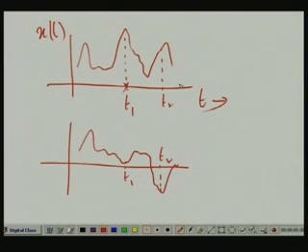This is possible. Now in the case of a stationary process, we assume something about this randomness. What is the randomness? It is the tendency of this waveform to fluctuate around the time axis. This time you got one waveform, next time the waveform thoroughly changes, next time it changes again. This tendency to fluctuate from experiment to experiment around this axis does not have any bias over some zones of the time axis.